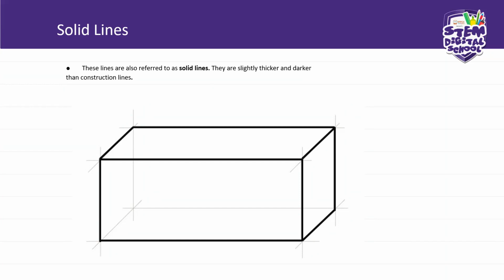Because the T-square gives you a straight horizontal line, because the crossing part of the T-square will hold on to your drawing board so that the line is really straight. But on the contrary, with your ruler, you might struggle to draw a straight horizontal line. And I also like the T-square because the other set squares will be moving along the horizontal line of your T-square. So it's important that we have the proper drawing tools.